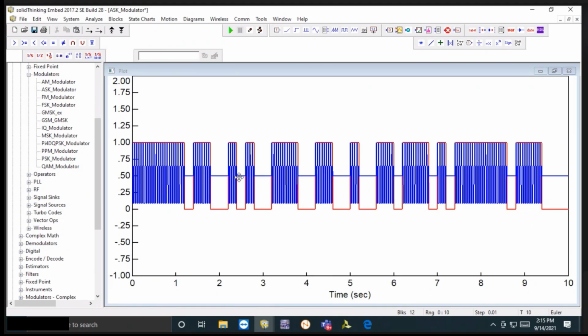So whenever there is a transition, from 1 to 0 or 0 to 1, there is a phase shift of 90 degrees. A phase shift of 90 degrees means at that particular instant of time, this is the instantaneous value. It is not like you will have to wait until this particular signal completes its period, and then it will change its phase. It is not like that. In the cycle, in the periodic cycle of the signal.